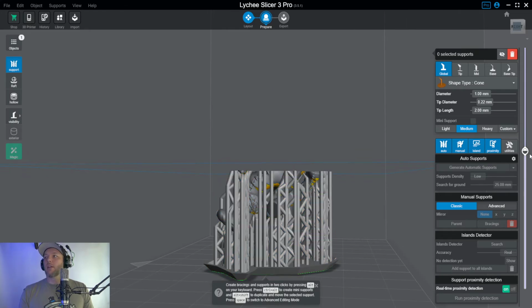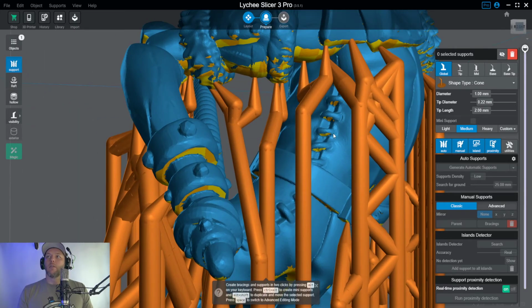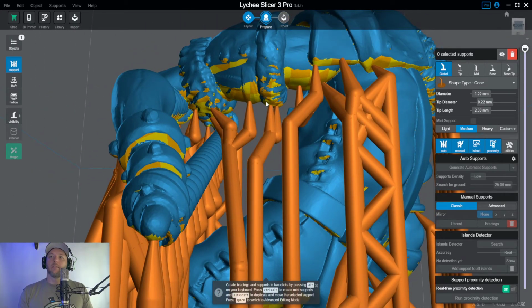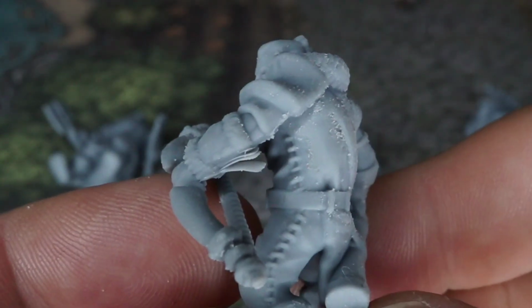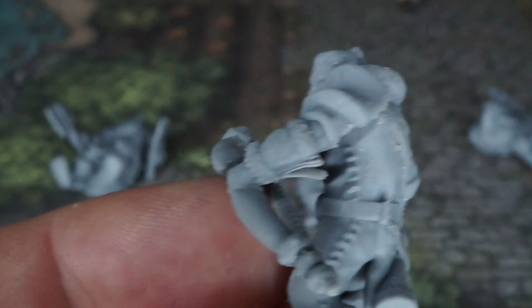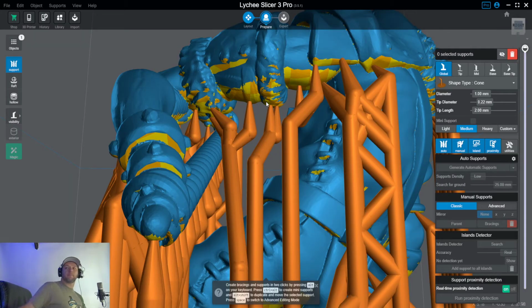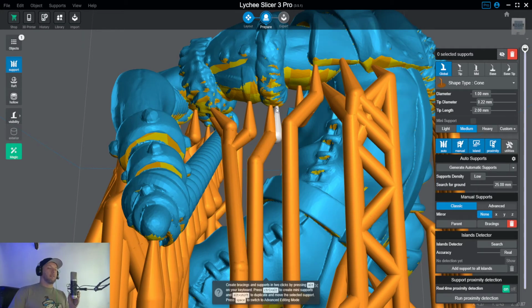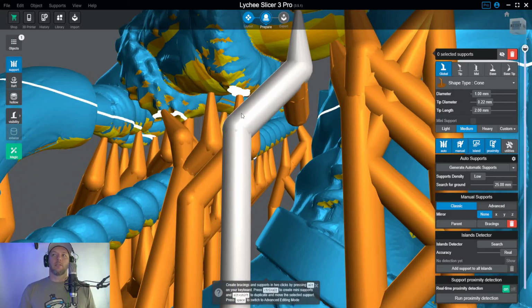All right, so let's have a quick look at our support. What do we think happened on this arm? Well, if we really look at that arm and where it failed, get the microphone here. It didn't really fail on the bicep, right? It looks like it failed right underneath the bracer. What it looks like is that these two supports here just weren't enough to withstand the forces.